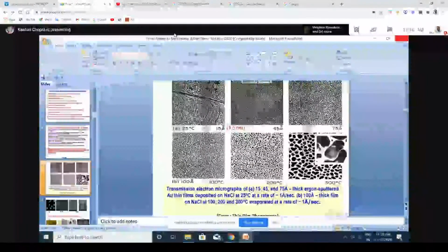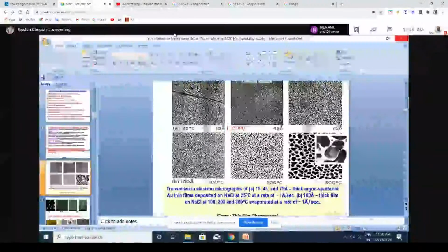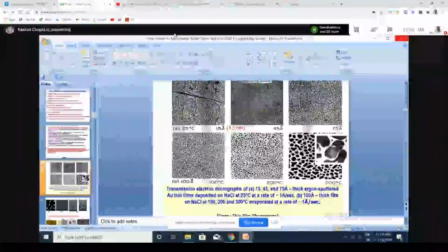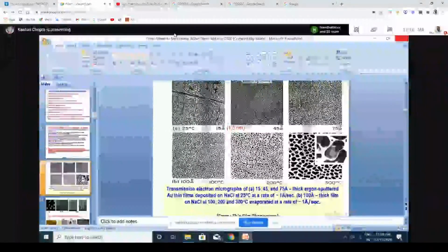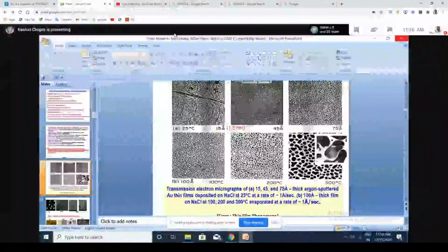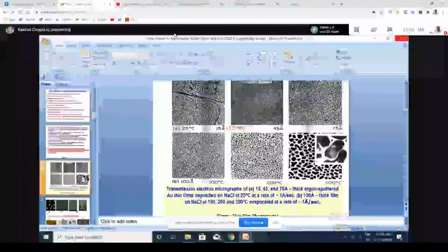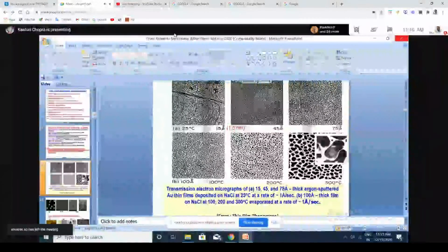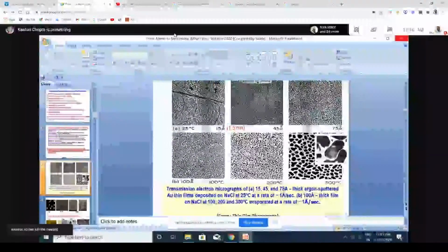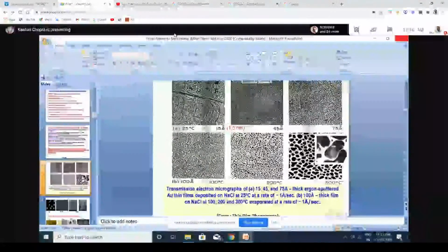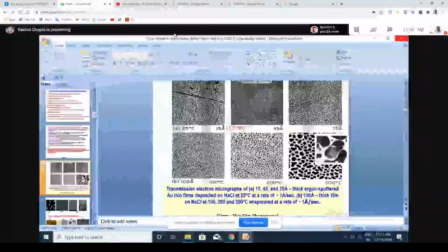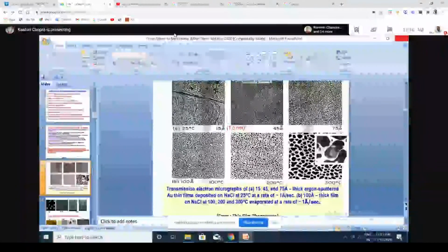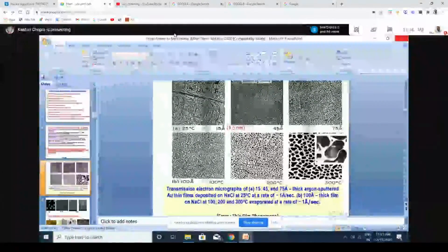As the film grows here, the small clusters become bigger and bigger, and then ultimately they combine together. When they combine together, naturally their lattices are different. Their orientation of the lattice is different. So they come together, they form a lot of defects. So thin films, normally polycrystalline, are very, very highly defective. Well, okay, that has advantage also, mind you. It gives them very strong strength, for example, mechanical strength. For example, gold thin films are 100 to 200 times stronger than bulk gold, much stronger. And this is very useful for space applications, for example.